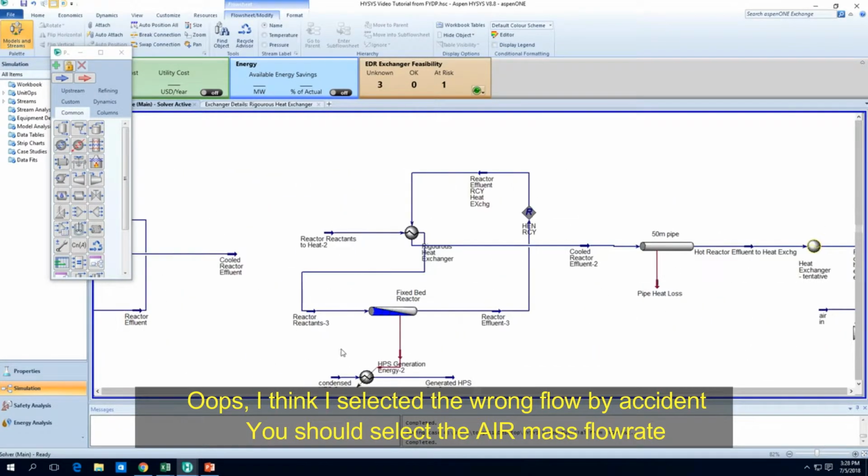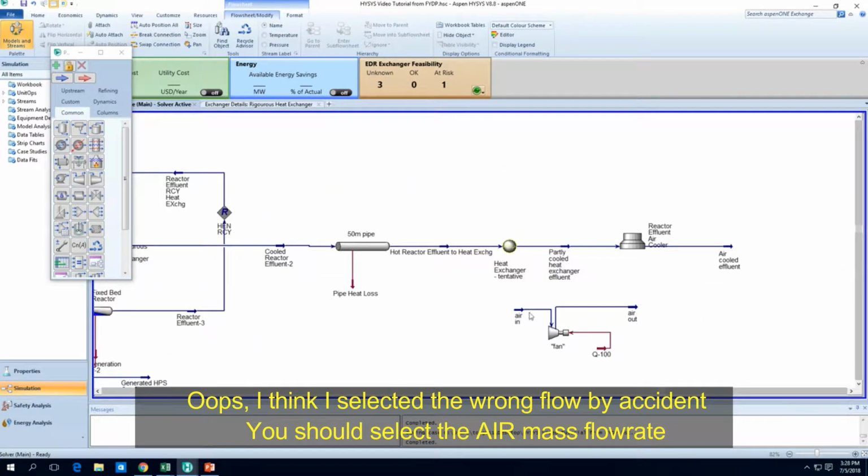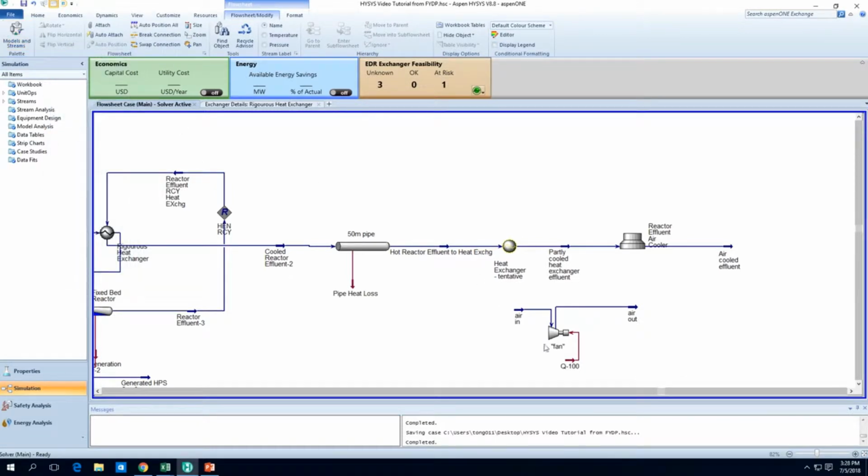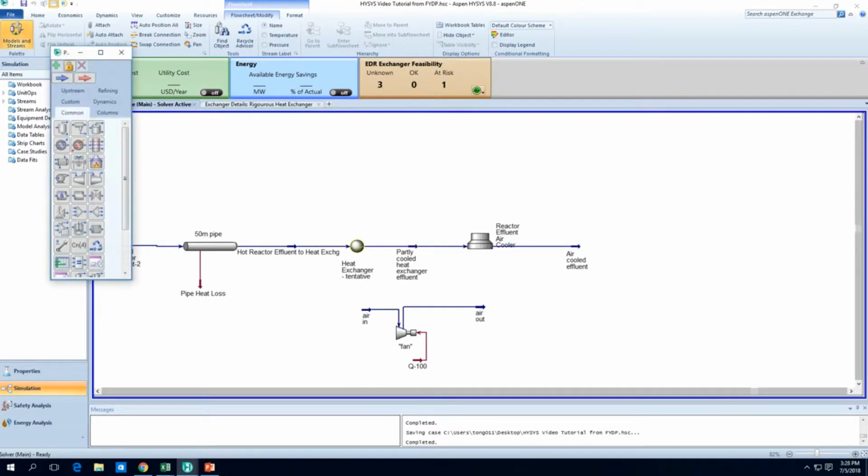Not a lot as compared to, let's say, a compressor, which is going to change the pressure by a few tens of kPa. And you can see why air cooling is very cheap, because there's so little energy being used. Okay, so that's a duty estimation. That's one basic, very simple way of estimating duty for our air cooler. So basically we use a compressor which we pretend is a fan. That's pretty much it for estimating the duty for our air cooler.